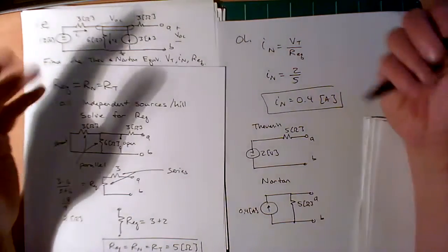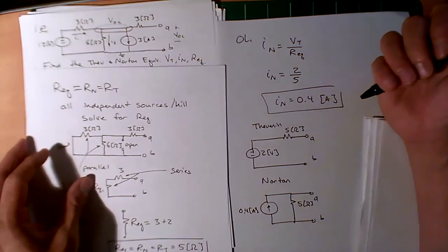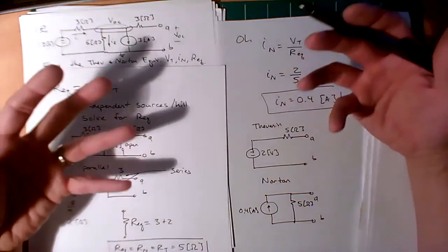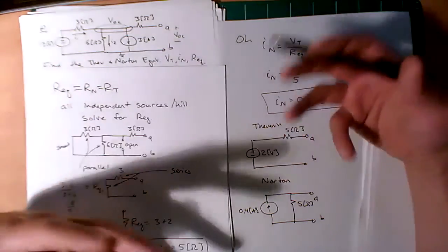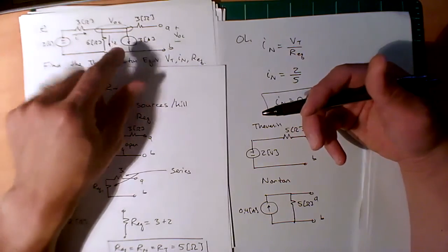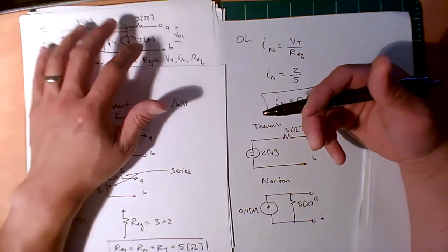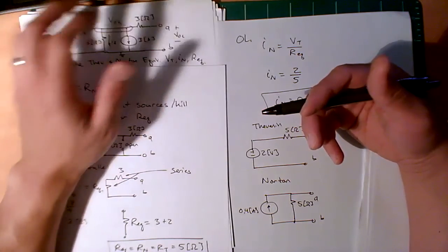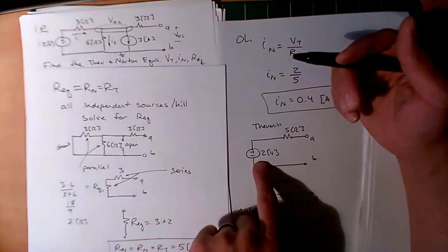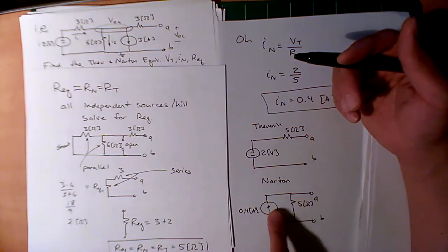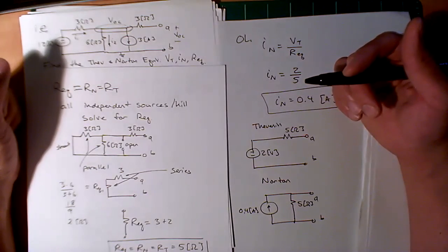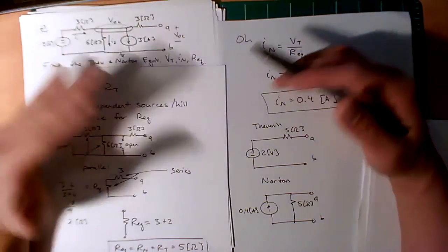Again, I want to repeat, this process is very similar to reducing equivalent resistors. If you have a bunch of resistors in parallel or in series, you know how to convert them into something very simple. This is the same idea: you have a bunch of voltage sources, current supplies, and resistors jumbled up. How would you chip away at it and reduce it down to a simple voltage supply and resistor in series, or current supply and resistor in parallel? Neat little trick, and hopefully this whole idea and process makes sense.